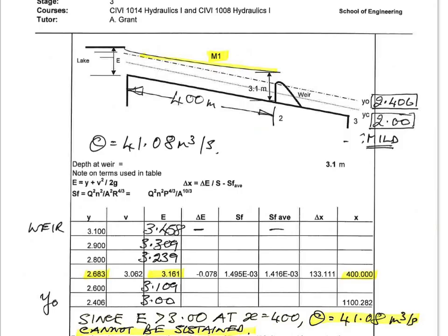So finding the discharge is a standard procedure, and we've just outlined how it is done, and the illustration and the numbers we're using were part of this question, and we may as well just look at the rest of this particular question just to illustrate a further thing that we are often asked in such questions, and that is, what if we have a downstream structure? Will the flow that we've just worked out be affected by the presence of this downstream structure? In this case it happens to be a weir, and we were told what the depth was immediately behind the weir.